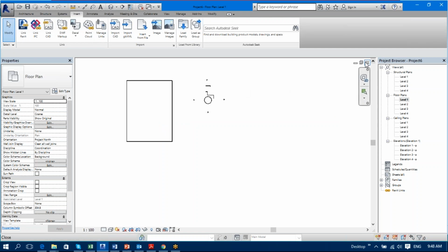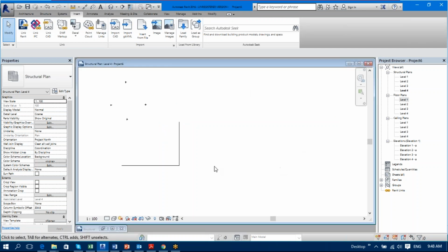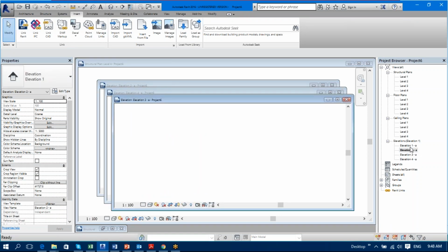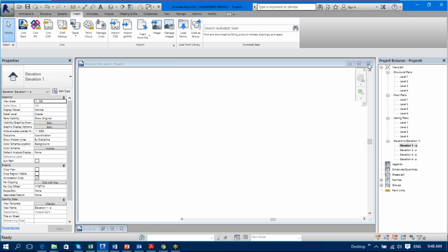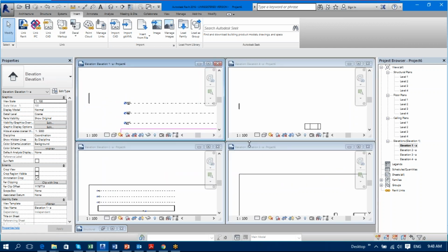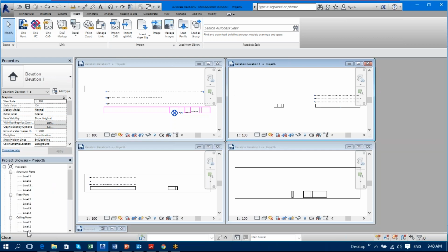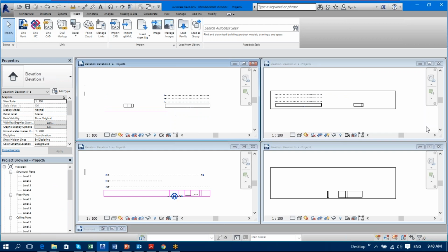Now my question was, I put a WT here. I have now 4 elevations. So we were working with levels, so let's open every level, and I switch it off. I'll press WT. I'll press ZA, zoom all, and I just drag this project browser because I have short space, and I'm going to drag it to the bottom of my properties palette. Cool. Now I press WT, I have more space.